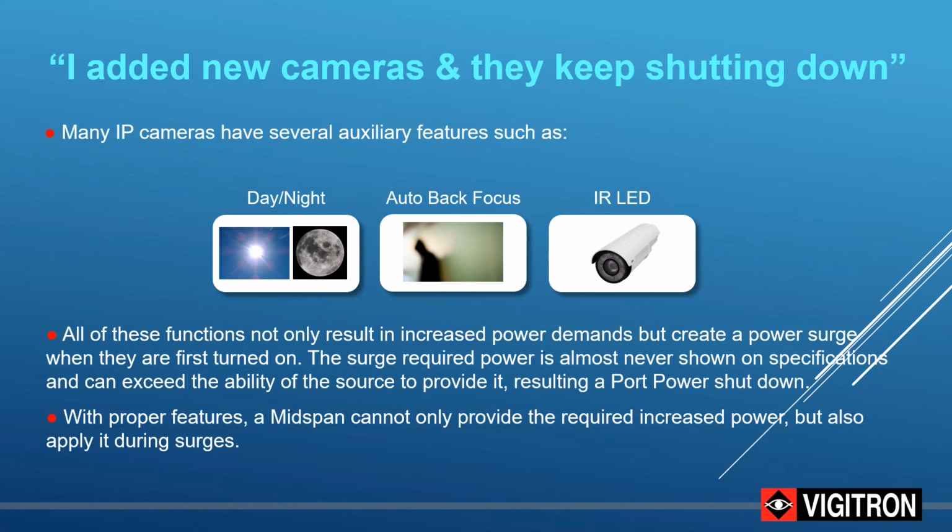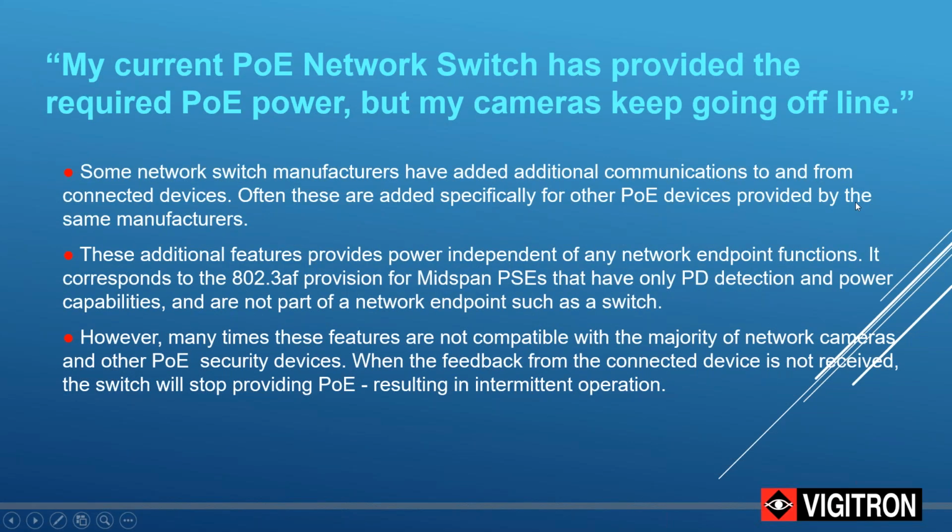Your midspan can add certain features to your system, such as the ability of monitoring the line, and should surge power be required, provide that extra surge power, or if your camera does go offline, have the ability of automatically restarting it and providing PoE. So another example of using midspans is not only the ability of adding power to your system, but also adding connectivity and reliability features. Basically, there's a lot of things that can be added to the system without having to replace your network switch.